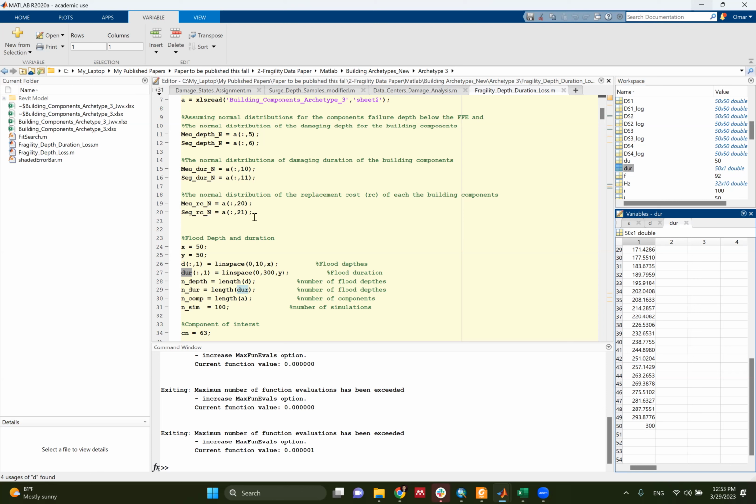We are saying that the flood water will stay a little bit over 10 days, for the structural damage. So we assume that if the building is soaked in water for 10 days, you are losing the structure as well, like the framing. Can a flood do this? Yeah, because you'll have maybe scour in the foundation, settlement, so lots of things can happen in 10 days.